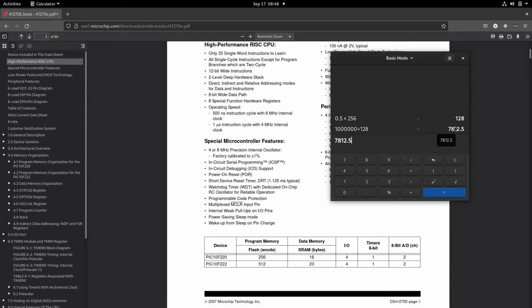And as long as it's just like your monitors and LCDs and other display stuff, as long as you are over 100 hertz, generally your eyes won't be able to see the flicker on our signal on the LED. So let's try to configure our timer.